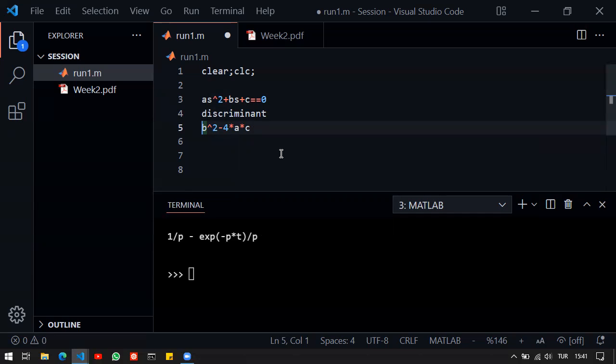And based on the characteristics, I can also conclude what the step response would look like, about the transients especially, because in steady state, it doesn't matter. In steady state, we will have just a static gain because this is a linear system, the transients are gone, and it would be just a gain. So, yeah, the solution here is important. For example, I know for now that if this is a real valued polynomial, if all the poles or both of them are real values, there will be zero overshoot, for example.